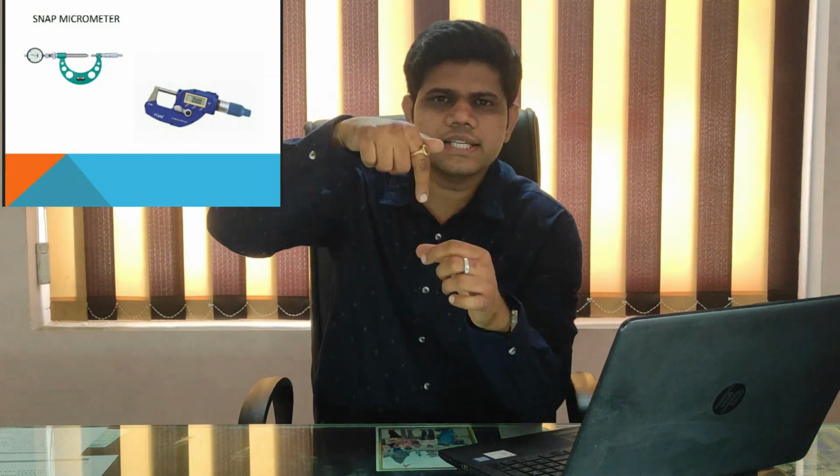In this type of micrometer, when the job is placed between the two parts, that is the thimble and the movable part, you will get the reading on the dial. You have to set the micrometer with the master slip gauge once, make it 0 on the dial, and then place your job inside that portion, and you will get the deflection in the dial.